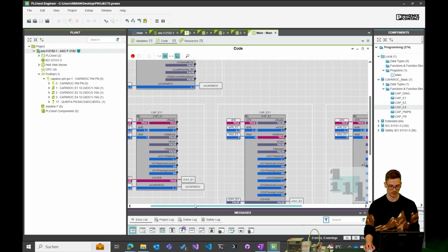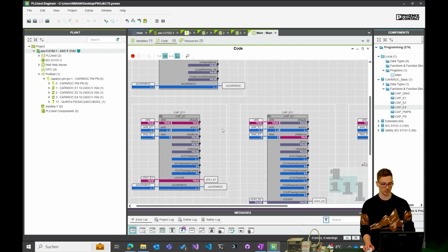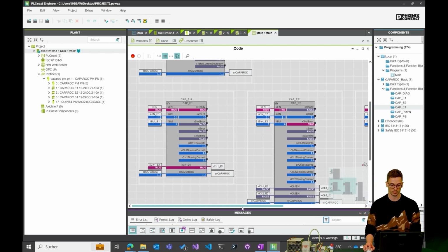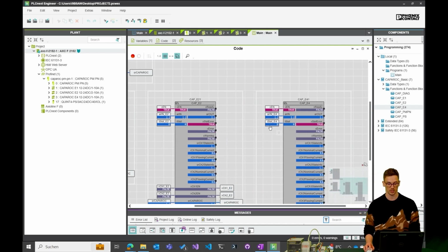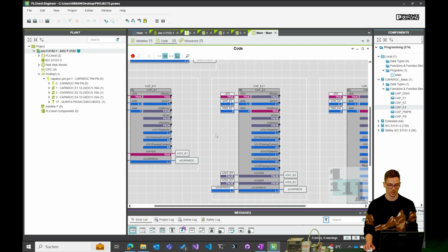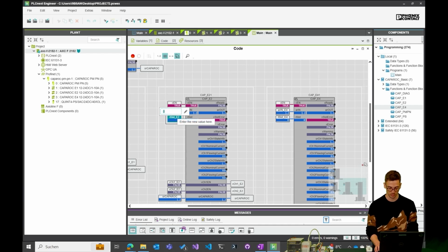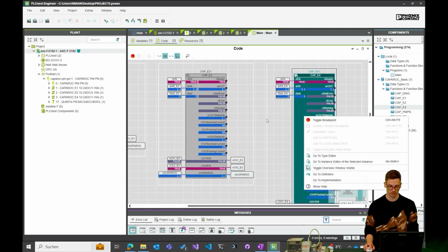You can see here there's no... this is a function I wanted to show you guys as well. If there are two of the same slots for the circuit breakers, it will throw a slot error, because it's not allowed to have two circuit breakers attached to the same slot. I mean, it makes sense, but you can see here, you have 2 zeros here, so let's put this to subslot 2. So this is ready now, and this one to subslot 3. It gets ready.